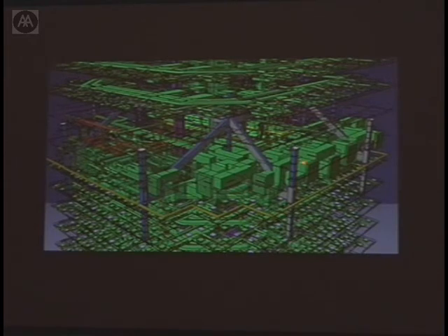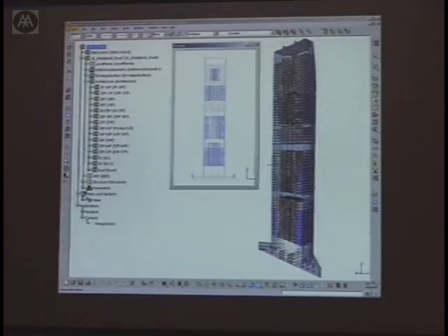because here we can see we have these diagonal brace frames, these outriggers, and the outriggers, if you saw them in plan, they're not just coming off square, they're also coming off at an angle. So this thing is really kind of going diagonally through space. And what we have here is basically this piece here winding around this diagonal beam here. And given the tightness and the amount of equipment happening in that mechanical floor, there really is no other way to wind this thing around. So being able to actually coordinate there is very important.